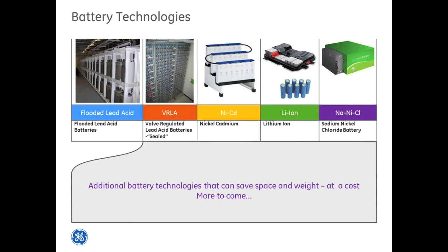Other technologies, VRLA, valve-regulated lead-acid batteries, the sealed lead-acid batteries, have found a way into many, many applications, even in central offices. Lots of cell sites and what have you, using VRLA batteries. Then some places are using nickel-cadmium, lithium-ion, sodium-nickel chloride, each with their own set of advantages, but at a cost, and we'll talk more about that.